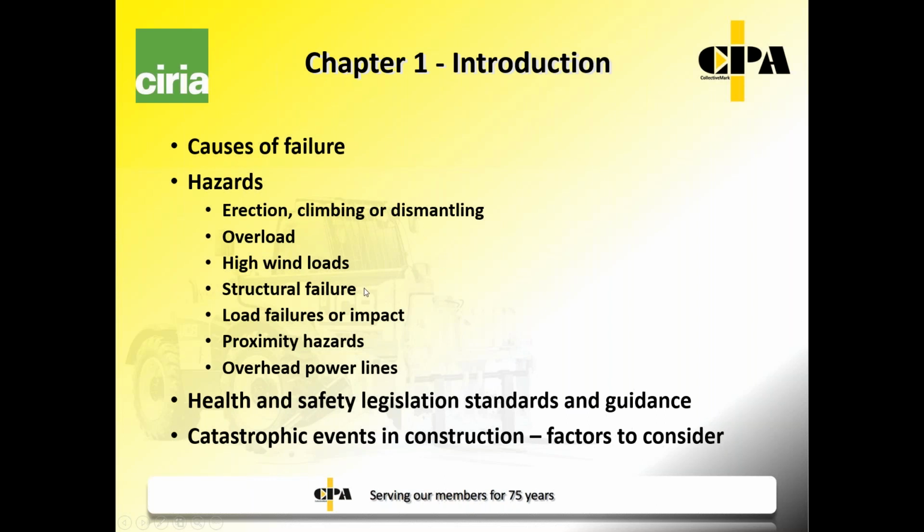Structural failure: you can end up with structural failure of either the crane or the base, very often due to fatigue, which should always be spotted by appropriate inspections and thorough examinations, but doesn't always happen. The other problem you can get is the failure of the load. The load may disintegrate in the air, or it may be dropped from the crane, and that will obviously have an effect on people nearby, or it may actually put some very severe shock loading into the crane structure.